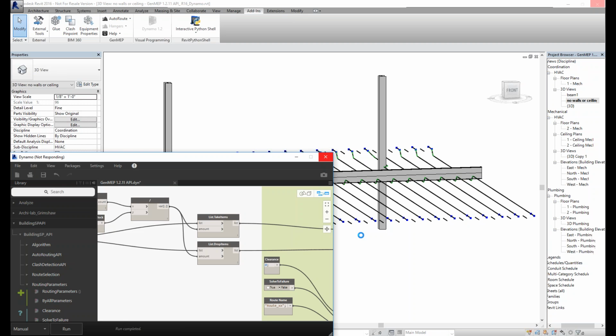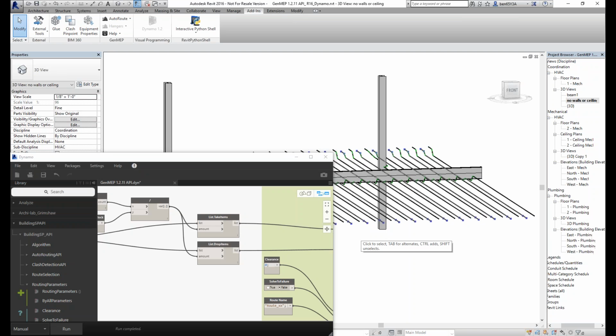And so we think giving the power of Dynamo to generate start and target elements lets individual users figure out good ways to do that on projects, right? I imagine a couple main ways this can help off the top of my head. If you have a Revit model that has electrical circuiting completed, you can use Dynamo to connect all of the Revit circuits. As you can imagine, a circuit has a start element and a target element, so you could auto route between all circuited elements in a model just by using Dynamo in one swoop. So that's a pretty good use case.